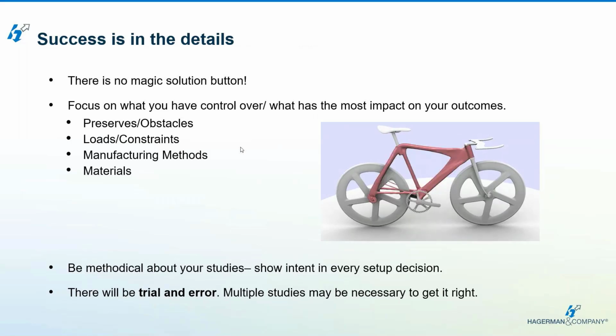So if we're throwing a huge amount of loads on there, or multiple constraints where they're not needed, or if we're adding too many constraints, then it's going to probably fail and probably not be what you want in the outcome. Also, with our manufacturing methods, we don't want to throw every manufacturing method on there. What I would recommend is we would do multiple studies on a design in generative design.